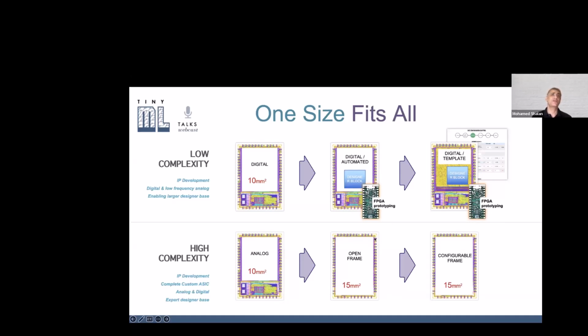We have a fixed configuration for the input-output pads, and you can use the silicon the way you want. Or if you are even more advanced than this, we can configure the pad frame for you, where you have the 15 square millimeters as a whole, and you do whatever you want with it, even when it comes to IOs.